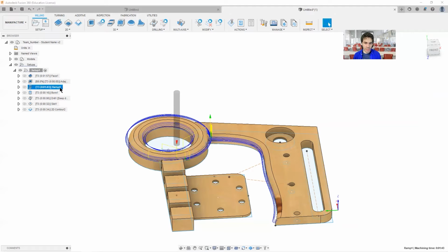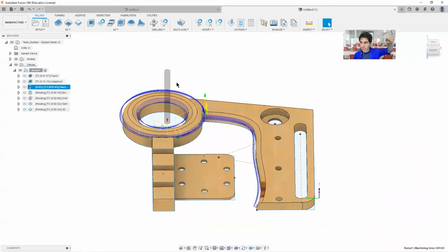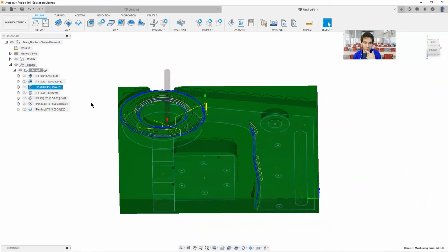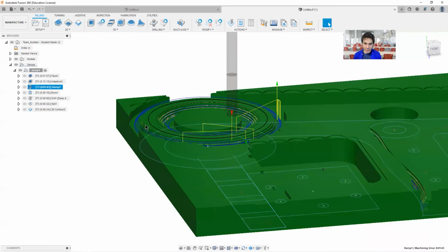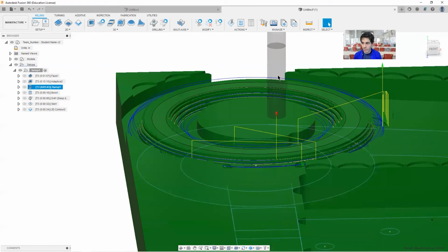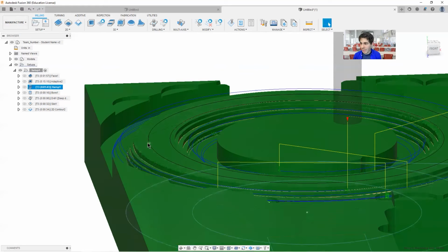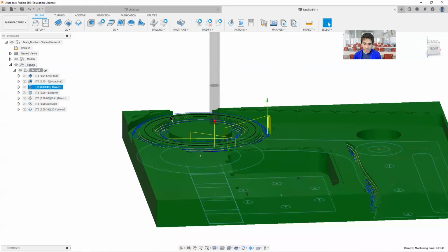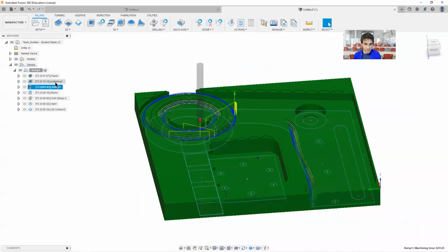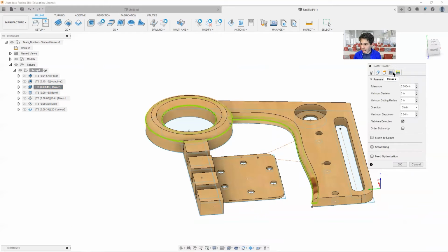A couple more here. We have a ramp toolpath, which is going to just gradually carve its way into our material. It's good for getting even contours, especially when you're using a ball nose end mill with a flat end mill. We'll still be able to get some of this done, and then you could conceivably go back in by hand or with a random orbital sander and smooth this out a little bit. If you want, you could even take the ramp at a shallower angle.